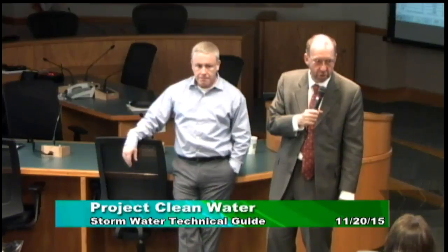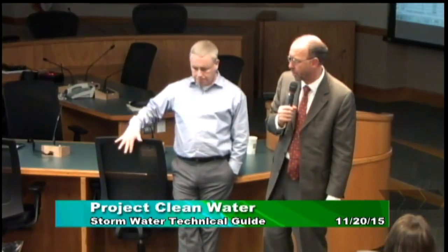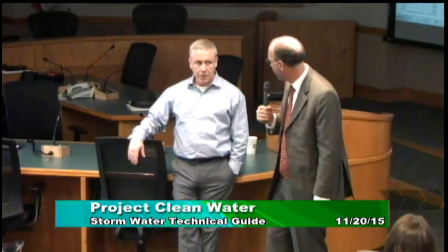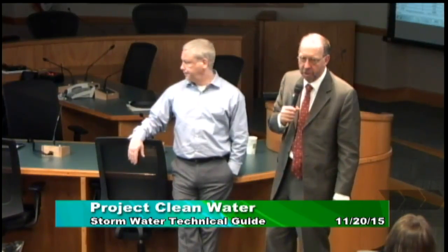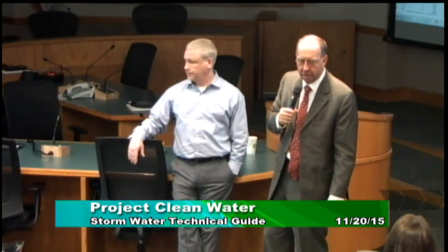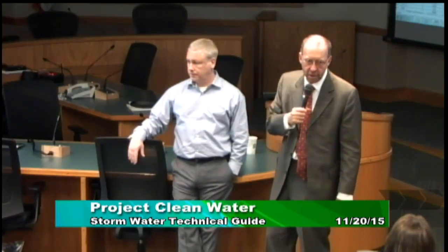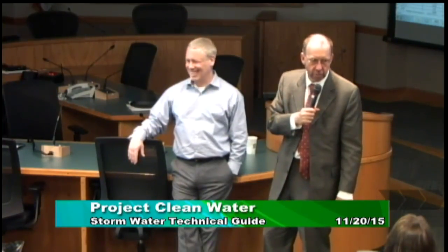We did negotiate with the water board. I guess I would call it a negotiation, that for CD soils, you still use 0.25 inches per hour. And we actually had some evidence for that based on some work we did in Contra Costa. And I don't think there's any particular limit. If you have 4 inches per hour, you could show it. The question is being able to convince that that's a sustainable long-term rate based on infiltration rate testing.